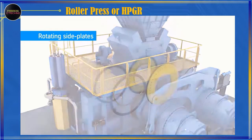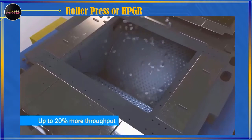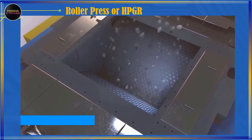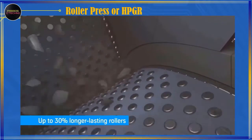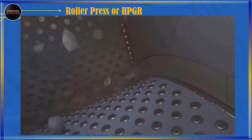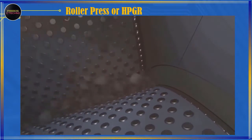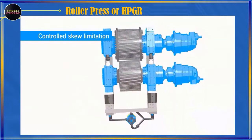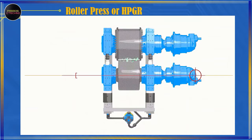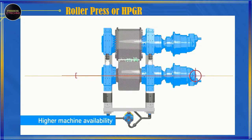The rotating side plate at the roller ends and the improved material feed enable up to 20% more throughput than conventional HPGR, while cutting energy consumption by around 15% and increasing roller lifetime by up to 30%. Wear protection segments protect the side plate, and can be adjusted or replaced without removing the rollers, which saves time. The unique controlled mechanical skew limiter uses a mechanical locking device to limit the movable roller's skew. The roller can thus adjust to different feed conditions, resulting in safer operation, fewer outages and downtimes.